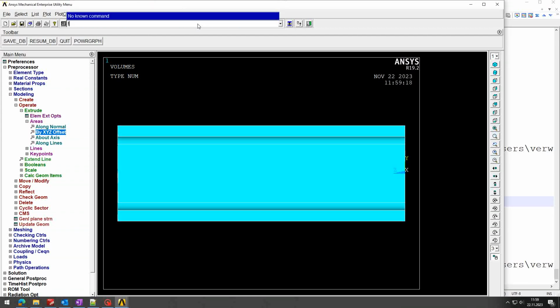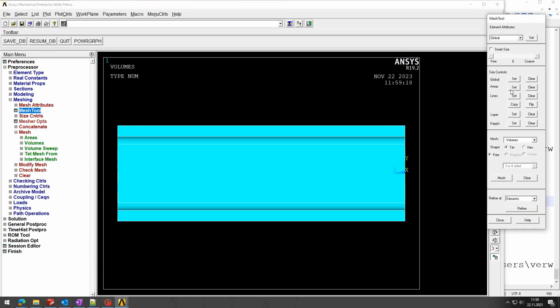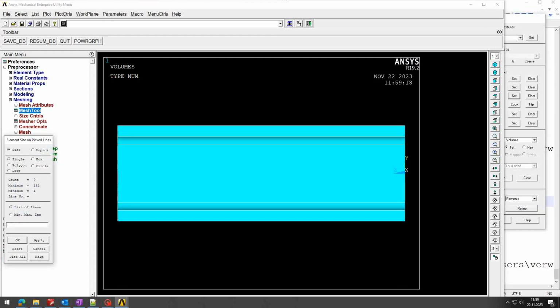So I'm going to put the side view, and here I'm going to say save the file, a comment here. I'm going to write creating line match along Z axis, and I'm going to go again to the matching tool, match tool, and I'm going to select here the lines set, and with a box I'm going to select all the lines that are along this direction.